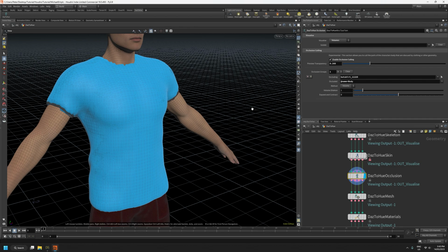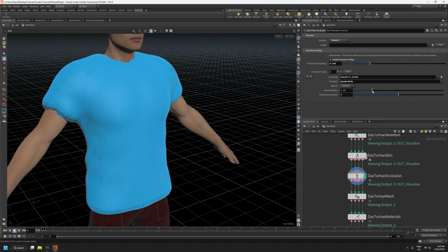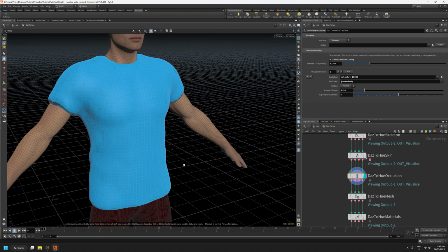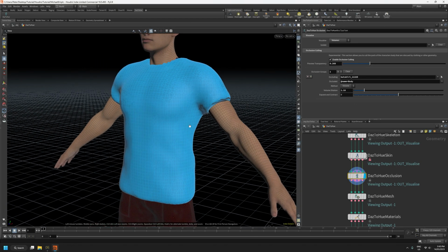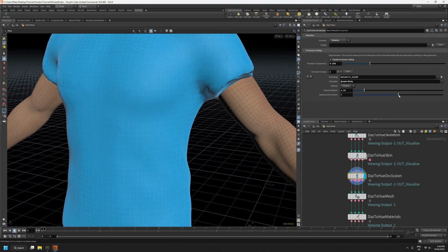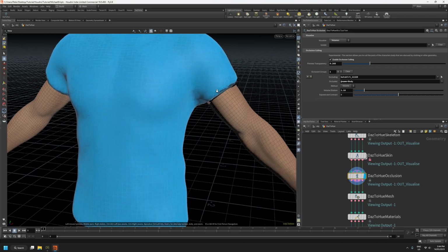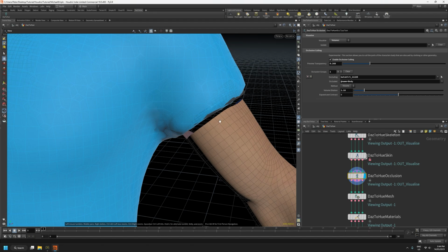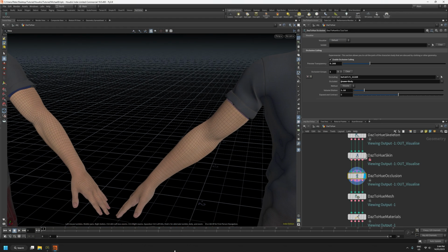And with the volume method, we get two options. We can effectively inflate it to increase its size, or we can deflate it. The other option, which is difficult to see in this visualization mode, basically it will expand or contract the points that have been flagged for deletion, and it'll do that for each geometry strip. So if we expand it, we will be deleting more of these geometry strips, and if we contract it, we will be bringing some of them back. I think it's actually easier to see that in the normal view.